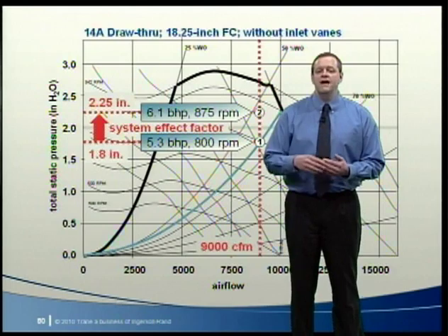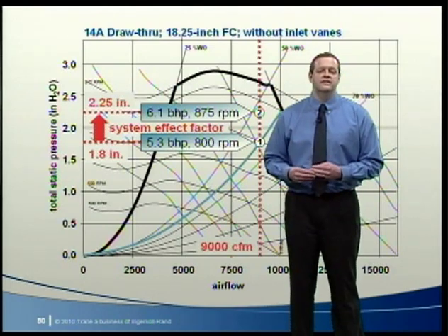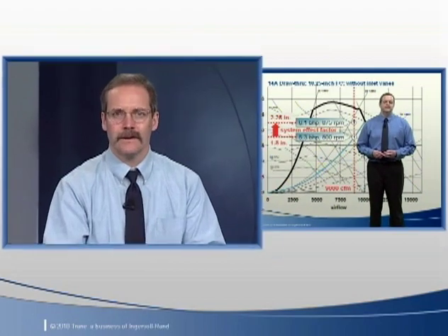So to have your fan perform as desired, pay close attention to how you connect ducts to the air handling unit. The acoustical impact of fan choices has been mentioned already during this broadcast, but let's take a closer look at how to select a quiet fan.